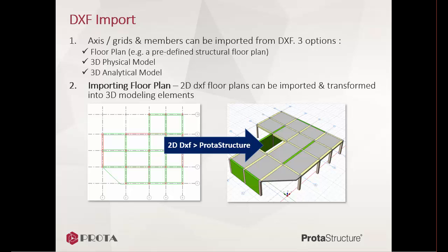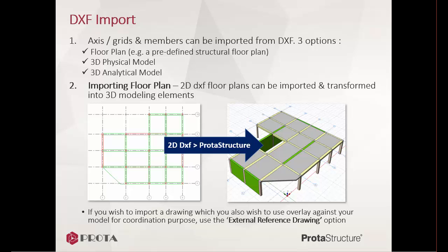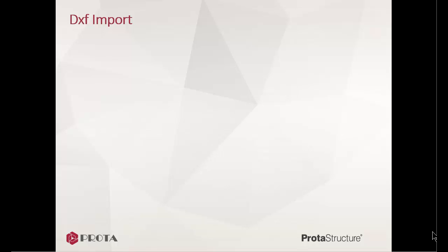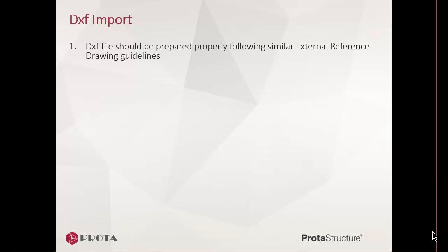If you wish to import a drawing, which you also wish to use as an overlay against your model for coordination purposes, use the External Reference Drawing option. There is an icon for DXF import in the same dialog. The DXF file should be prepared properly, following similar external reference drawing guidelines.